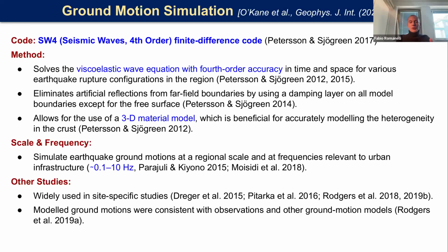Let me tell you, I think if you have reached 10 hertz as a modeling, as far as I see here, 0.1 to 10 hertz, if you move to acceleration, the profile that you're getting is going to be very variable there, and it will be very sensitive, keeping the fault scenario, but the rupture scenario will influence it. So the scatter of, for example, PGA will be much more variable than the PGV there.